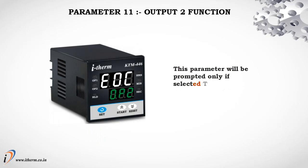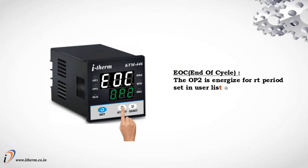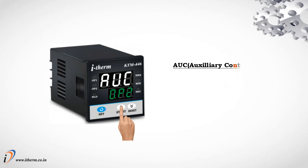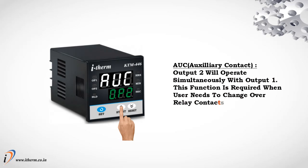Parameter 11, output 2 function. This parameter will be prompted only if selected timer function is other than cycle 3. End of cycle. The output 2 is energized for RT period set in user list at the end of timing cycle. Auxiliary contact. Output 2 will operate simultaneously with output 1.